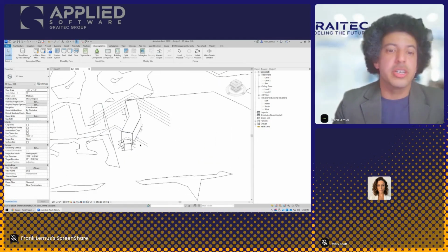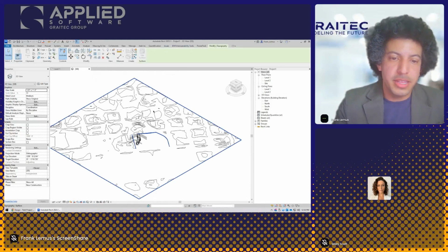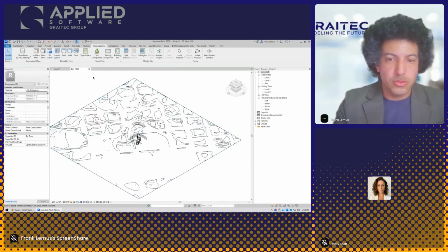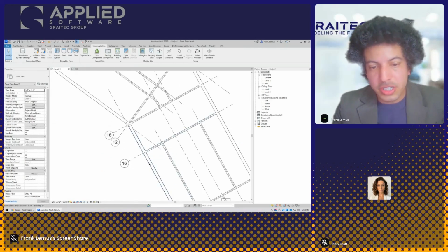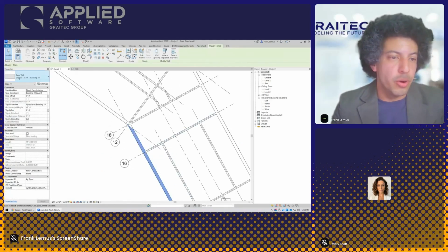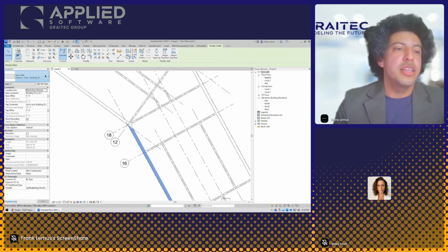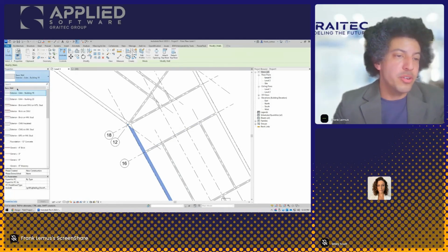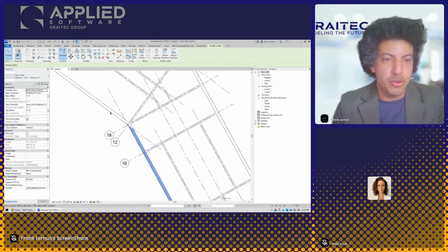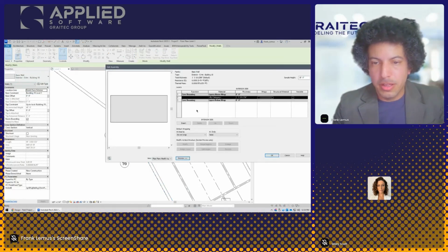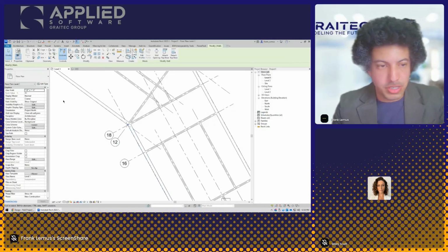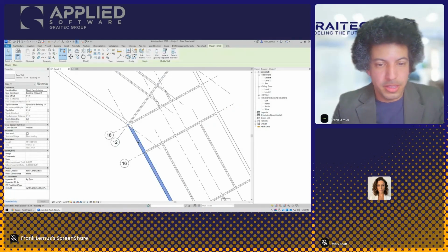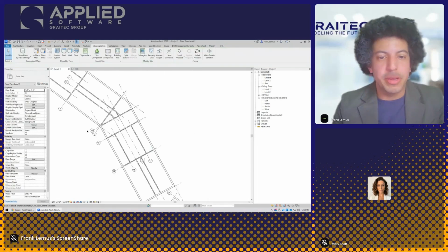So it's taking me over to 3D. You can see that yes, it's giving me the actual surface of it there, and it's giving me geometry. Notice this geometry is actually a wall. These are actual walls. This may not be what you want. For example, see it's creating this type for you, just a basic wall of a particular strange thickness. You might want to go in there and change it. Of course, make sure you consider the location line of that before you make changes.